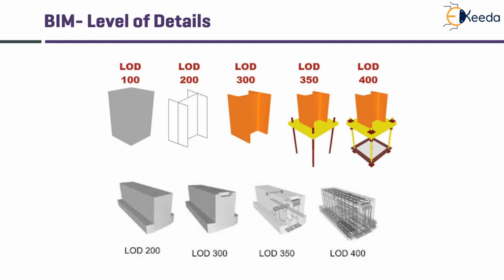Similarly, for a RCC beam or girder in LOD 200, it is only a concept design showing a rectangular shape. LOD 300 shows minor cuts and offsets.